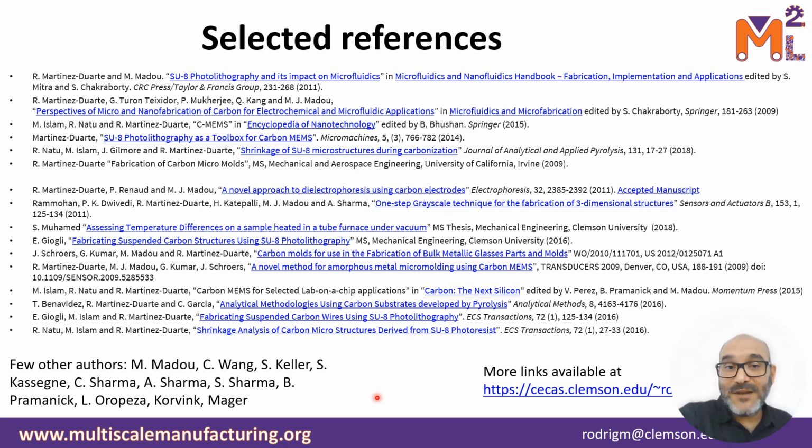So with that, I would like to close this particular processing approach. Remember, this was a photolithography to create the precursor to the carbon, right? After we get these photoresist structures on a particular substrate, we will put them into the furnace and heat treat them with particular ramps, as you will be seeing throughout this summer school, in order to create the carbon that we're interested in, right?